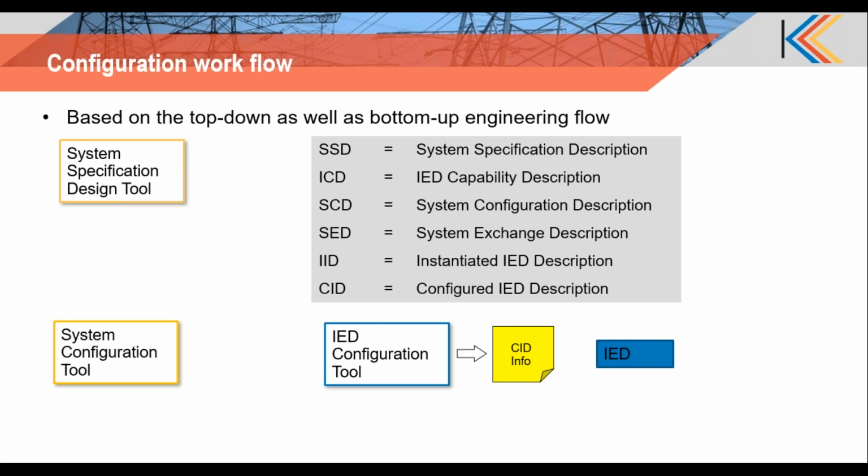And it also has to have a valid configuration of all the information it should subscribe to. This constitutes the data mapping philosophy. Data mapping is the mechanism by which you configure which data goes from an originator IED all the way to the destination IED. So that's the data mapping configuration.